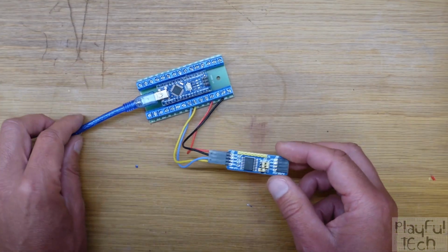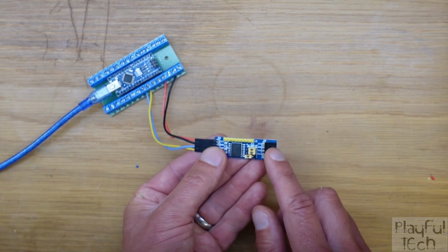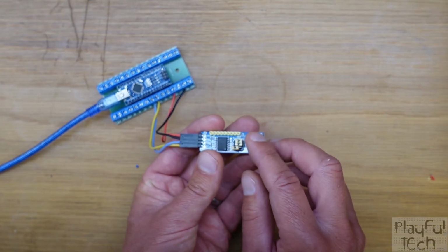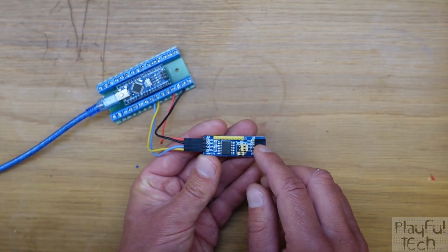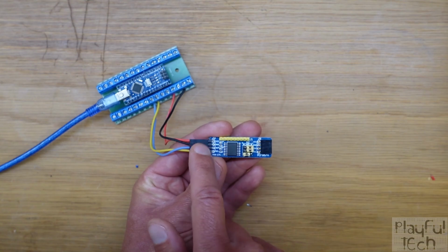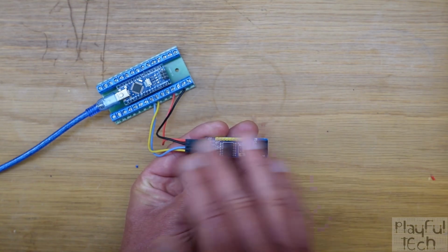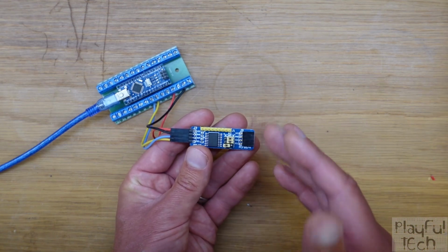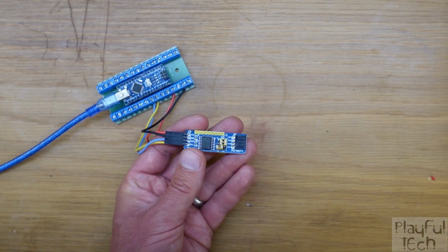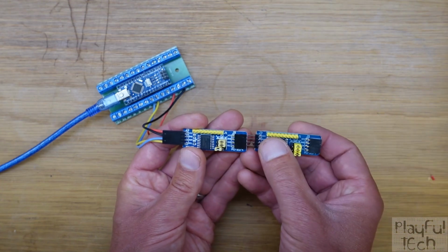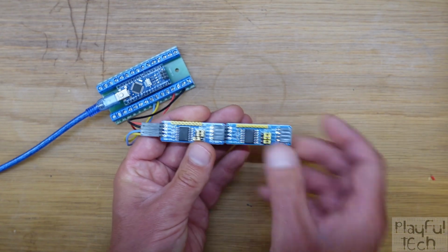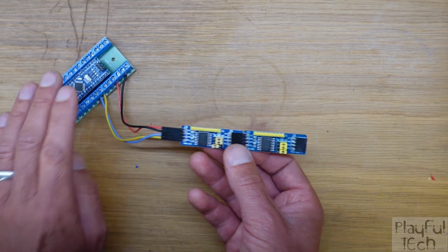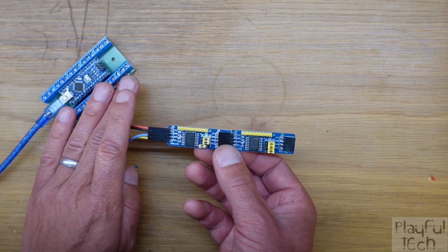But it's about to get even cooler, because at the end of the board here, you'll see that there are 4 more pins. And these are the same data and clock, VCC and ground lines as at the other end of the board. They literally just pass straight across the board and out the other side. And because I said I2C was a bus interface, that means we can plug more and more I2C devices onto the same bus without using any more GPIO pins or making any differences to the Arduino at all.